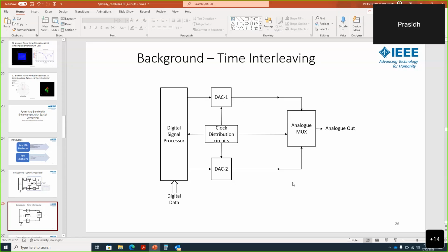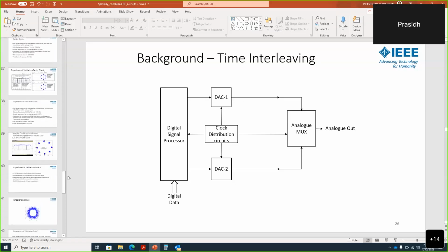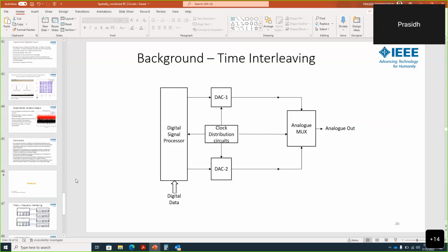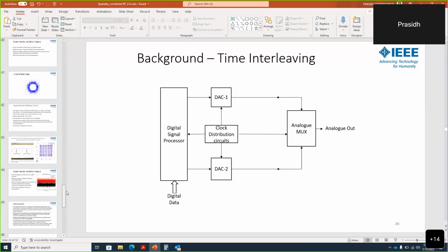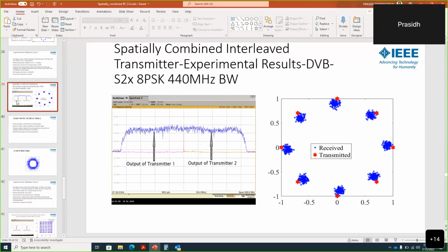then mitigating that is not going to be as straightforward as in the frequency interleaved case. In the frequency interleaved case, any component falling in the adjacent band can be visualized as a two input and two output system. So then basically you can derive its transfer function and invert that. There have been publications on that. So it should all be doable in the digital domain, with a software correction.